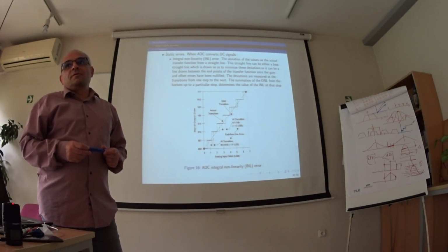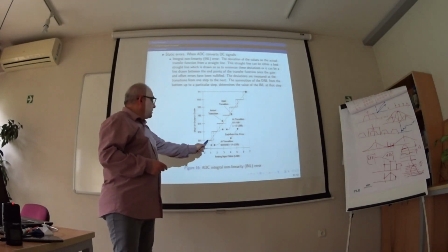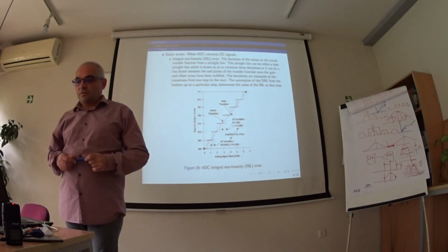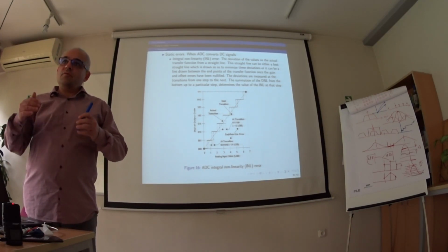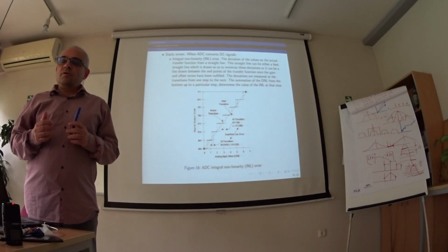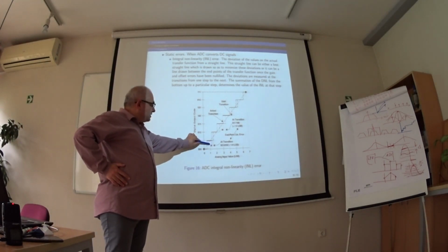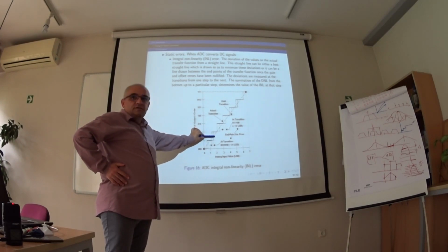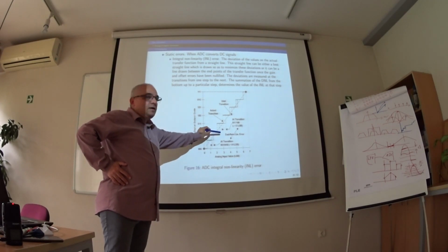Yeah, but how would you get it calculated? Is it the variance or deviation of the step size? Deviation of the step, yes. And it's different for each one? No, the error is different for every step. You have differential non-linearity of some value for this step, and some other value for this step. They are independent of each other. When you sum them, you get the integral.